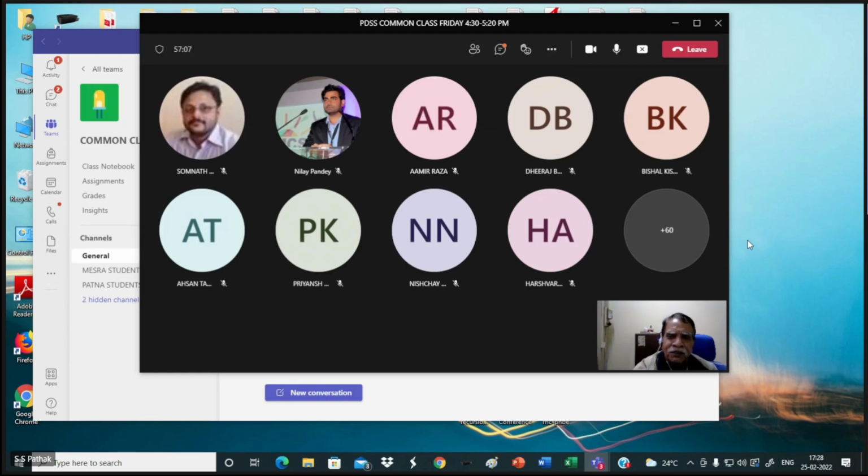That is the thing that you must remember, because the capacitor voltage is calculated using V initial and V final, the initial value of the output and the final value of the output. Based on that, I can find what V naught is at a particular time t. Anyway, that has to be considered here.